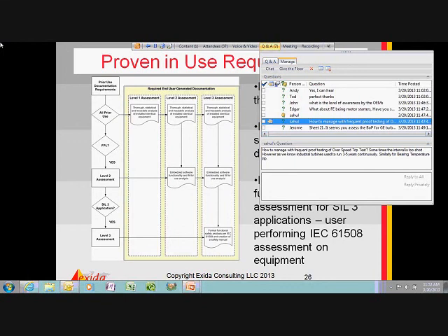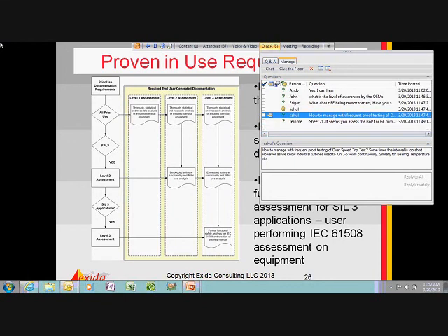So you have to model that test at whatever that test interval is going to be. If it's 3 or 5 years between tests, then that's what you have to put into the calculations, which can drive down the risk reduction factor.